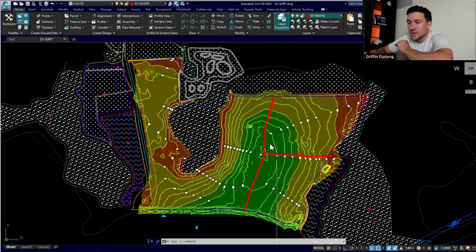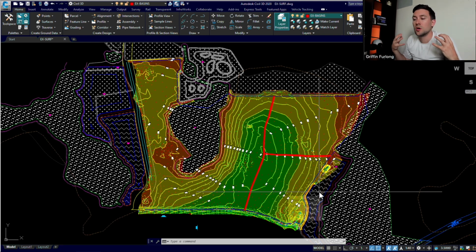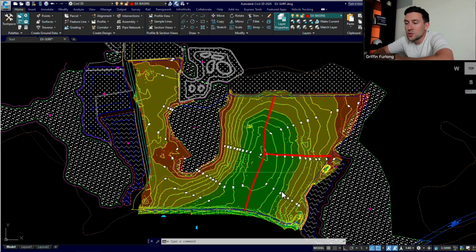Okay, so we've definitely partitioned off some of these basins, right? And again, a basin is the area in which water is going to drain. Any water droplet that falls within this area is going to go to some sort of point of reference or a node, a storage unit, or it could perhaps be sheet flow into a particular area. So in this case, we've delineated this basin where water is flowing into this pond. So we've developed this on-site portion of basin that flows into this pond.